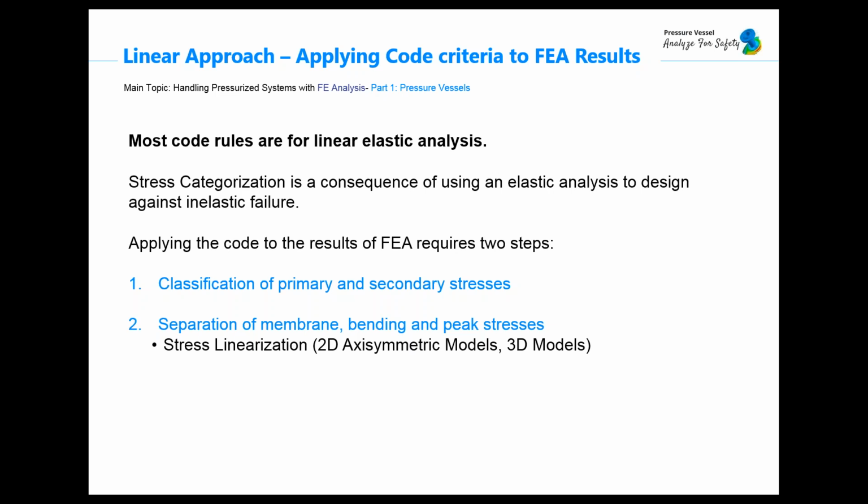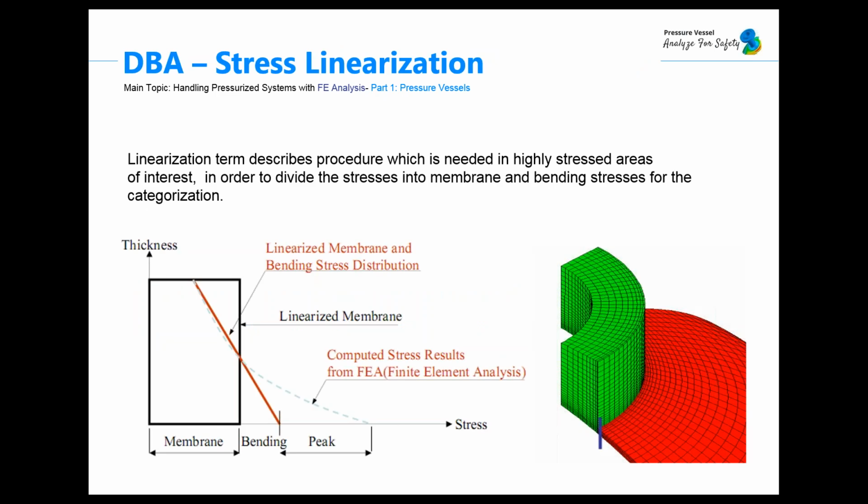But in case of three-dimensional analysis, as I started to say before, the stress at the point is defined by 6 components. Usually those components are oriented with respect to the global coordinate system, and these results are not in agreement with the code requirements. Due to this fact, a technique called stress linearization has been developed, and the method is widely used for separation, or we can say extraction, of pseudo membrane, bending and peak stresses from solid element linear results.